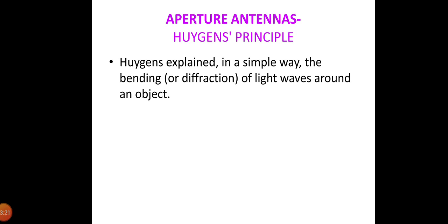The secondary source concept shows that the secondary waves will spread out away from the aperture and there will be a smooth blending of the lit and shadow regions. This diffraction effect is for a slit in an opaque screen with a plane wave incident on it. Huygens' principle evolved into the mathematical form referred to as the equivalence principle, or field equivalence principle. The field equivalence principle replaces an aperture antenna with equivalent currents that produce radiation fields equivalent to those from the antenna.